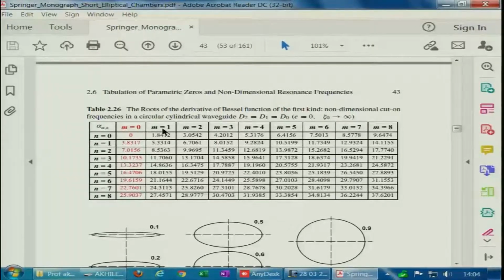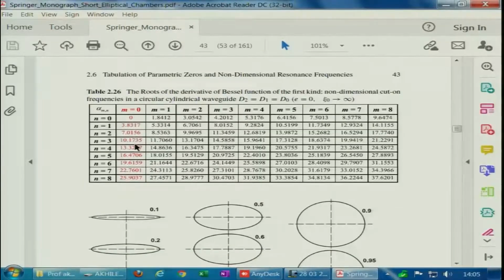For m equal to 1, 2, 3, 4 and n being 0, these are circumferential modes, but we will be considering only m equal to 0, n equal to 0, that is the planar wave mode, for which J 0 of 0, the argument of the Bessel function of order 0 being 0, you just have unity. So, this is a plane wave mode and it comes out nicely mathematically. This is the first radial mode, second radial mode, third radial mode and so on. These are the radial modes and that is what we will be dealing with.